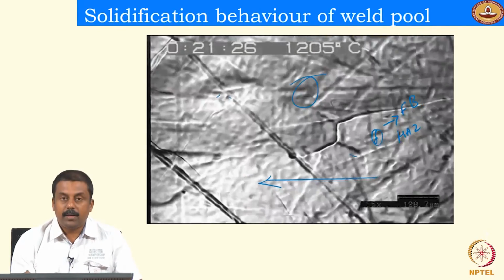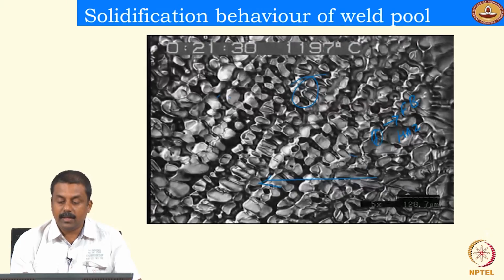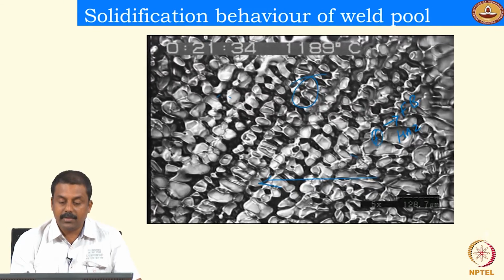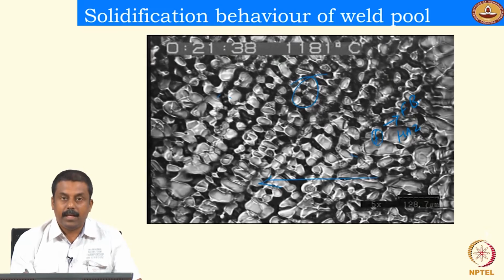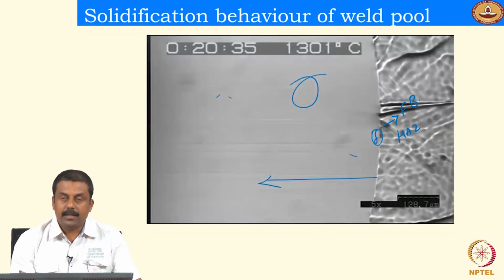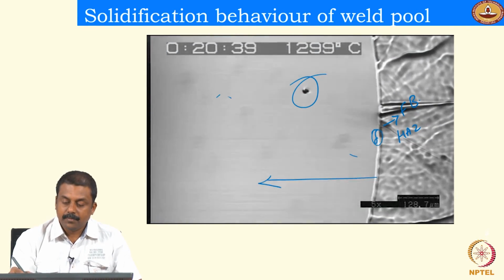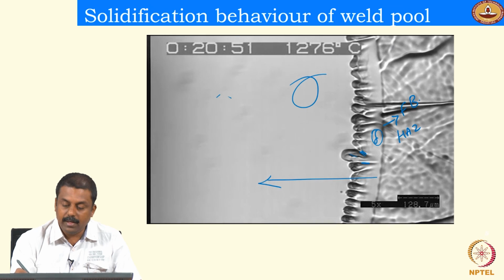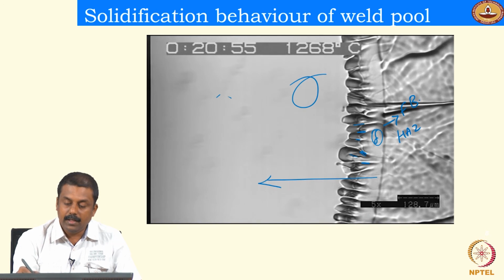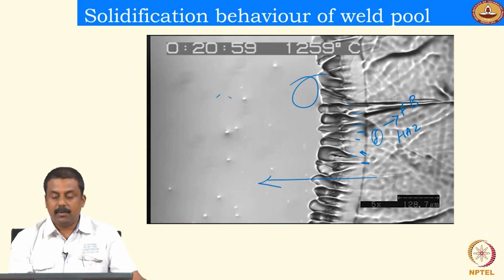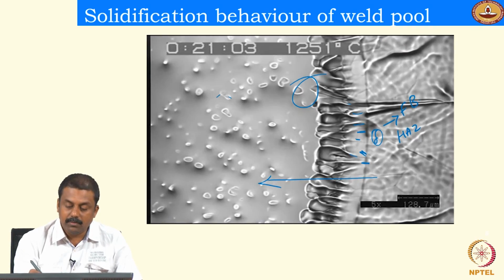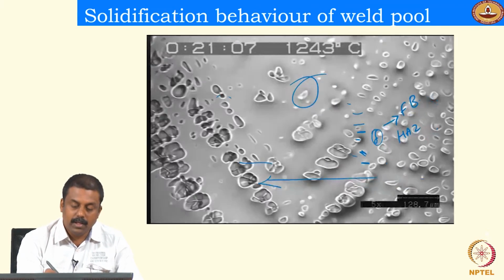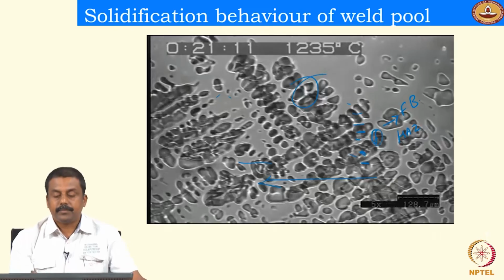So now the important thing you need to understand in this solidification is, when solidification begins, how the alloying elements are partitioned to the boundaries of the grains when you are solidifying, and subsequently how the carbon is also pushed towards the untransformed liquid.